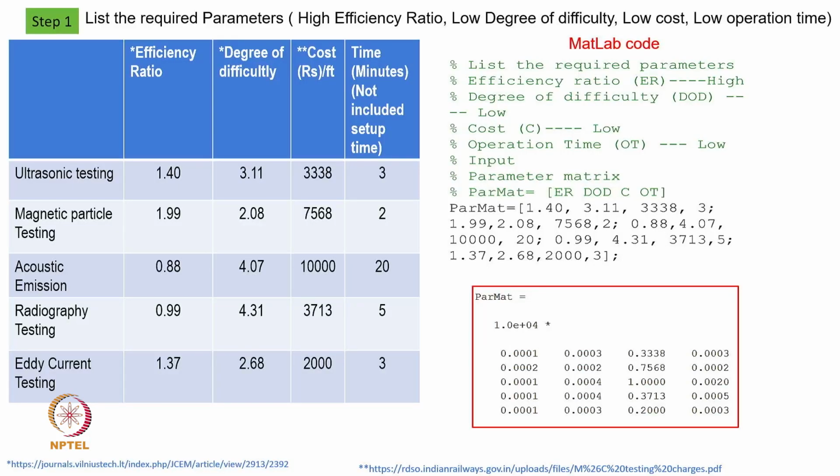And then another possibility, as I mentioned, is that wherever it is getting attached to other surfaces, or two different surfaces, then they crack at any one place. Naturally, initially the crack will be there, then it will continuously propagate. So, it will cause more problems. Now, if the crack itself is like a crater crack, which is bigger in size, like a volumetric crack, then more and more problems will be there. So, that is why whenever a weld junction is manufactured, NDT is a must. We should be utilizing NDT for that purpose.